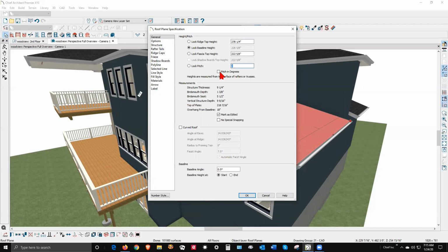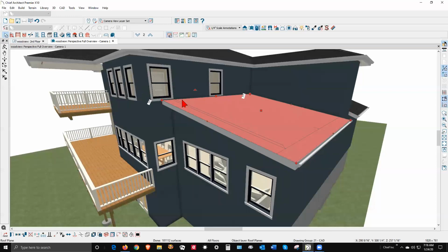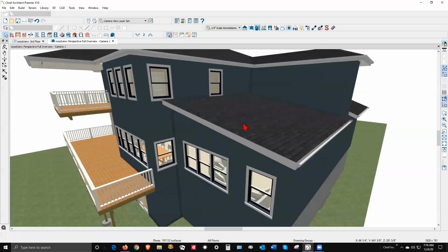And 312 would be the steepest you could have it, and then plan to roof it over with shingles, because with anything with a lower angle than 3, shingles won't keep the water out. So you'll have to put impervious roofing on this. See if 2 clears the windows. There, okay, that just barely does. So there's 212. Now you want this vaulted.